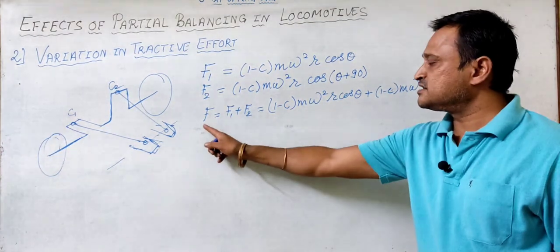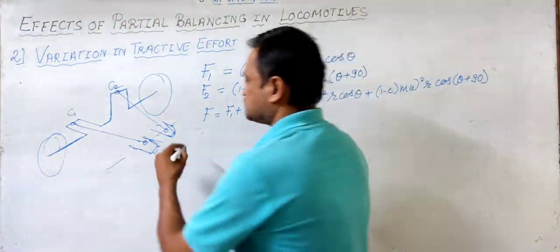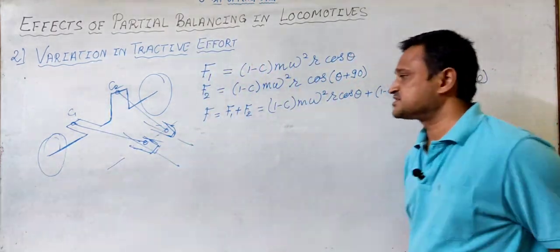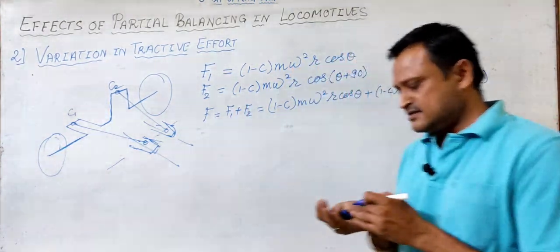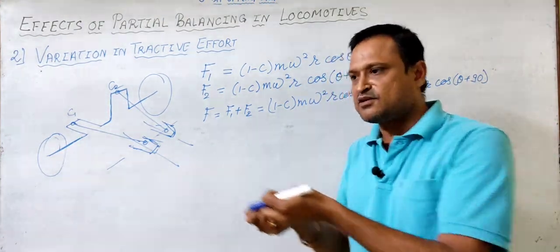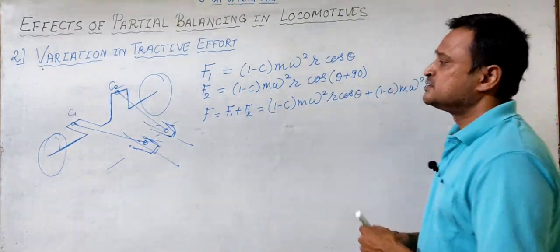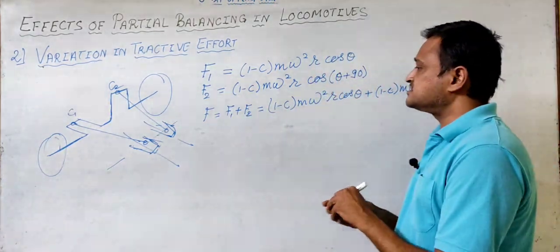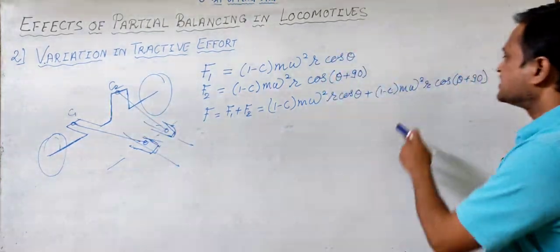So this will be the total force acting in the line of the stroke for these two, right? Sum of these two forces. So this will be an unbalanced force, as if at times it will be pulling the shaft or pushing the shaft with this amount of unbalanced force in the system. And this magnitude is continuously varying as theta is continuously changing.